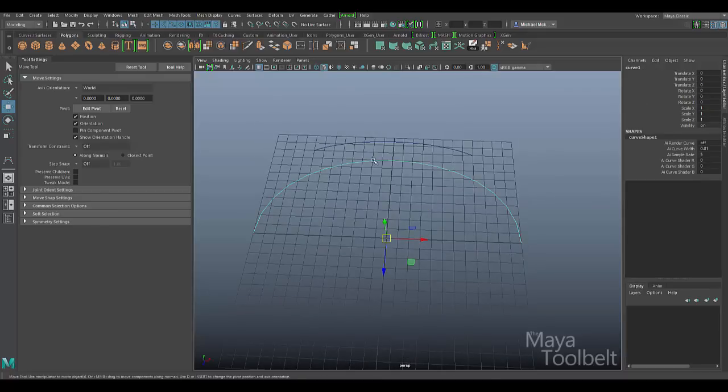Obviously, having the end knots visible makes the ends of the curve a bit easier to manipulate. With having them not visible, or having no multiple end knots, like with this curve, you do have a bit more flexibility when it comes to attaching this curve to other curves. You do have a bit more control over the tangency of curves that are attached to it.